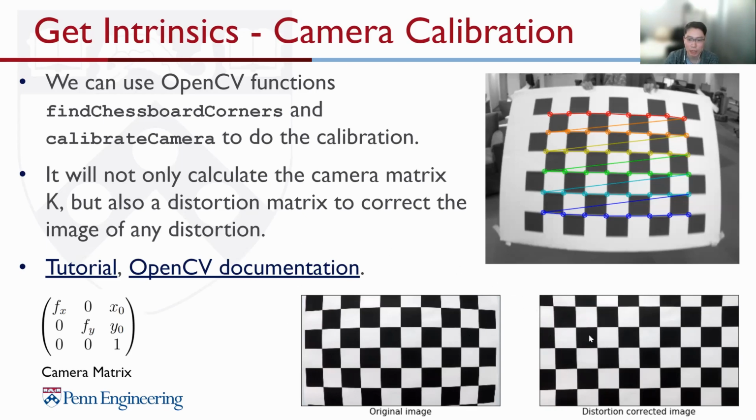But this would be an extra step if your lens is distorted. However, as we talked about, the ISP, image signal processor, can do this transformation very fast. So your CPU doesn't have to worry about this if your lens needs a distortion correction. So yeah, camera calibration, use OpenCV, we can get this camera matrix.